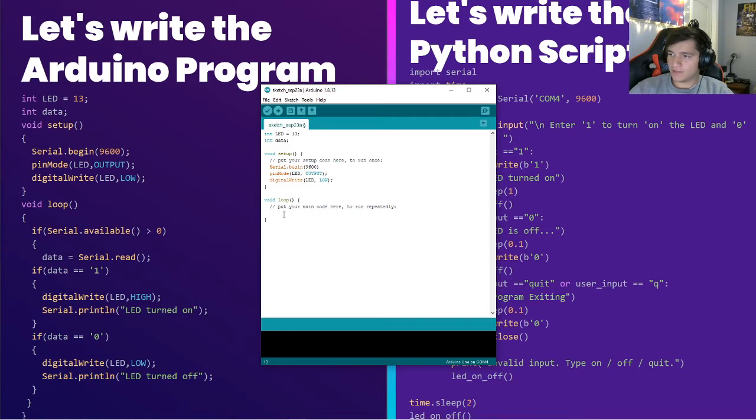So now within the loop, this is a loop that is constantly running. So throughout the whole process of the Arduino working, it's going to constantly do this. So what we're going to do is create an if statement. And this statement is basically a conditional statement where whatever is inside the if statement, if it's evaluated to true, then whatever is inside the curly brackets is executed. So here what we're checking is to make sure that the serial port is open. And if it is, then we're able to transfer that data from the Python script back to the Arduino.